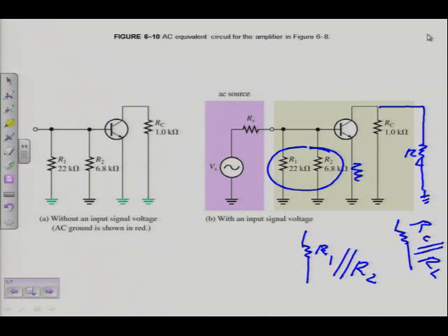So just keep that in mind. Don't go and learn these things like a parrot. You have to look at the circuit that you work with. Is there a capacitor over RE or not? A bypass capacitor. If there's not a bypass capacitor, then of course you have to leave RE in. Like on this circuit, if there was not a load resistor, then I cannot calculate RC in parallel with RL, because there is no RL. Then it will only be RC, for instance. So you have to look at the circuit that you were given. Don't go and memorize this.